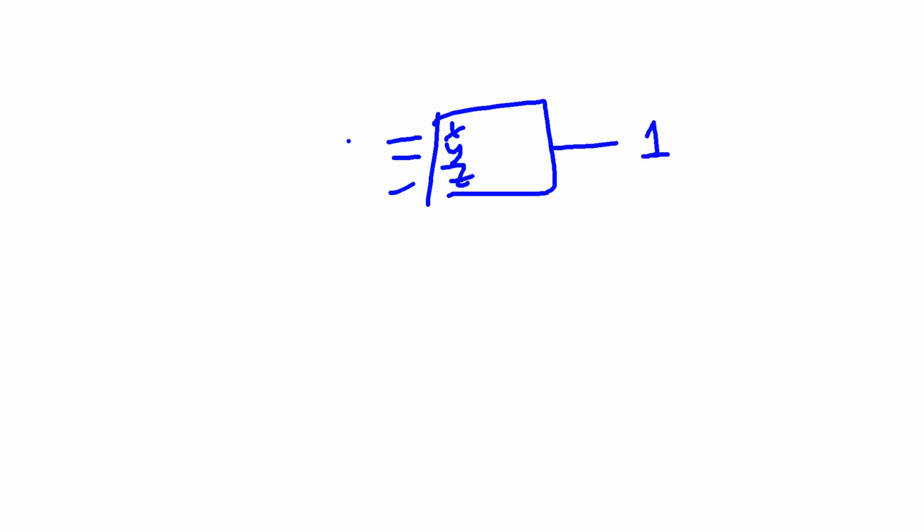First, more example. If I want x, y, z, the output becomes 1 when input is 0, 0, 1. What is the min term? Of course, it should be AND together between all input variables, right? It will be 1 when all terms are 1. But when you apply 0, 0 for x and y, it's not 1, right? So you must invert it here. That means the min term for this example is x prime and y prime and z.